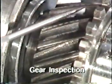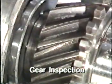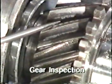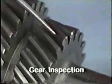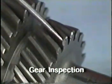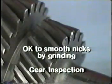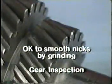Any abnormal pattern indicates the gear is not meshing correctly. Make sure the pattern doesn't extend off the face of the gear tooth and that the pattern is not unusually small. Occasionally, you'll find a gear tooth with a small chip or nick. When the chip or nick does not extend into the contact pattern, or extends into the contact pattern only from the top, or does not extend from the side of the tooth into the face, it's acceptable to smooth the nick or chip by grinding and reuse the gear.